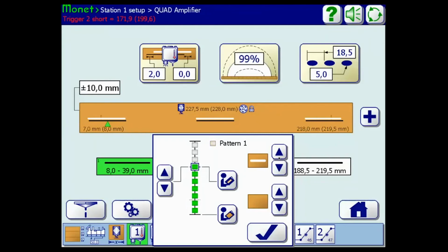I'm glad you asked that when you did, because I happen to have our lead engineer in here. Now, we can provide you a document that specifies 95 from the product to the top of the sensor. Okay. And then screw it on until there's 20 millimeters of space. 95 from the top. We're going to add that to the setup guide. It's easier to measure from there because you have the shield on it.